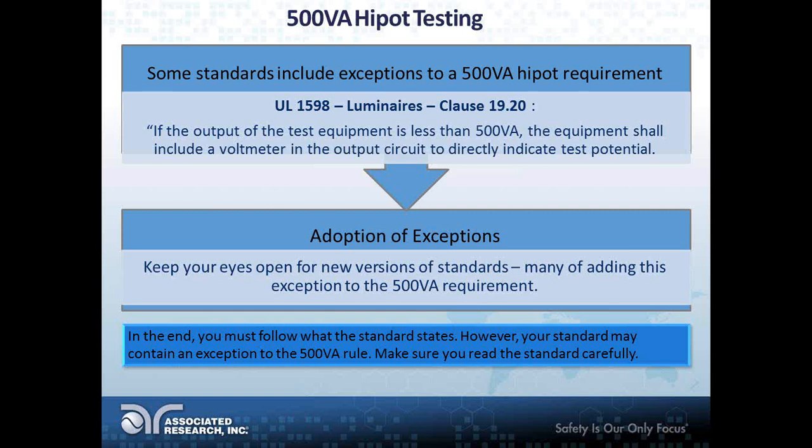Also, keep your eyes peeled down the road, because I've seen a lot of standards bodies working with guys like us to change these 500 VA requirements. In some cases, perhaps they're still necessary, but in a lot of cases, they're realizing that the technology has caught up, and that a lot of times 500 VA really isn't needed anymore as long as your Hipot tester can maintain the voltage output. So there could be some adoption in various standards in the near future that remove this requirement. So we'll see what happens. Hopefully you got some useful information on 500 VA testing. It's something that comes up quite a bit.